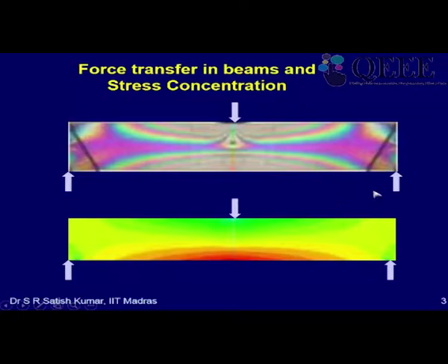One typical example is due to this huge stress concentration which you can see here, local plastification can occur at that place, especially in the web and all, things like that. Then this is also called a stress analysis, right? There is a stress analysis that we have done here, but quite often the beam may have instability issues.